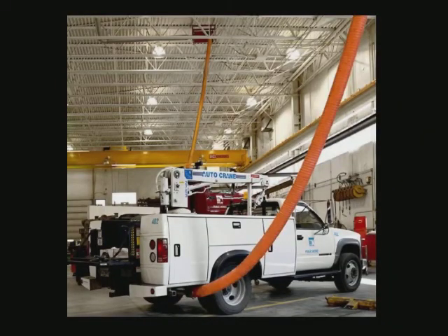All right, this is a picture showing, and I guess my thought process on this would be, if I'm designing a system, if it's an existing building, I would like to take a look and see exactly what's around the area that I want to handle with vehicle exhaust. And if it's a new building, I want to make sure by looking at the prints, what kind of obstacles will I see? This picture is good because it shows hose reels but it also shows an overhead crane. And if you look at this picture, it looks like that crane is going to come right towards those hose reels. So for this application, we utilized motorized hose reels because we can get that hose completely up out of the way of the crane so the crane can travel back and forth.